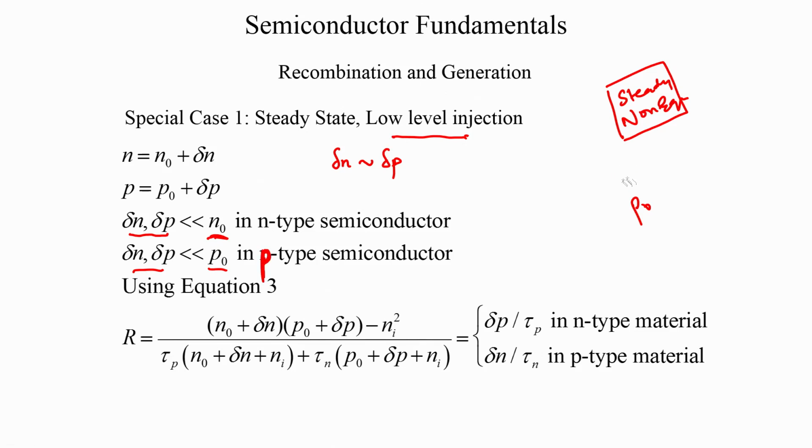Okay, so, just to give you some numbers, let us say we have silicon. So, Ni is 1E10 per cc, and we dope the silicon with donor dopants of 1E15 per cc, which means that the doped semiconductor at equilibrium will be, let us say, purely extrinsic, which means all the dopants are ionized, so in equilibrium my NO will be close to Nd, which is approximately 1E15 per cc.